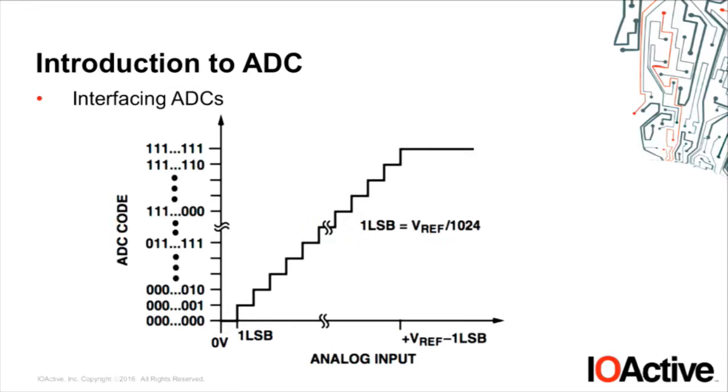This is the way these ADCs help us read what is in the analog world. It's basically summarized in this slide. We have a voltage reference, which helps the system decide the maximum value we can get in amplitude, and also describes each bit, because at the end of the day, since we want digital data, we're going to get a bit stream, right?